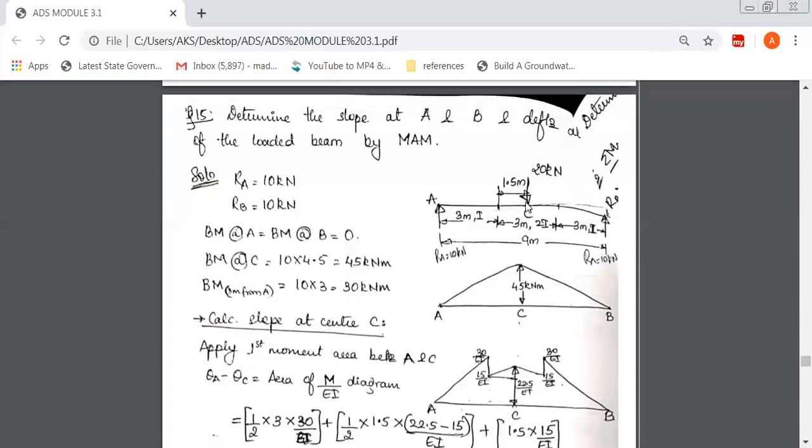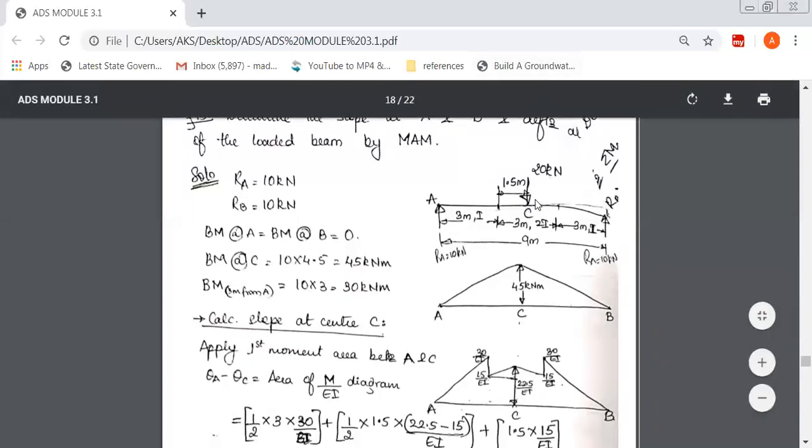So which gets equally distributed on both sides of the load. Because it is placed in the center, this 20 kilonewton downward load should be balanced by the supports. So 20 gets distributed here. The downward load is 20, so the upward load has to be 10, 10 each. Then the system is said to be in equilibrium.